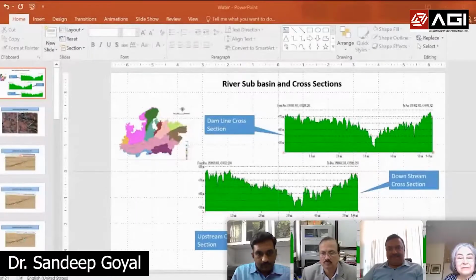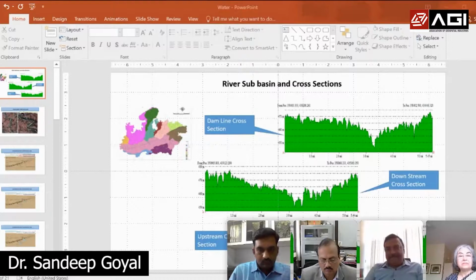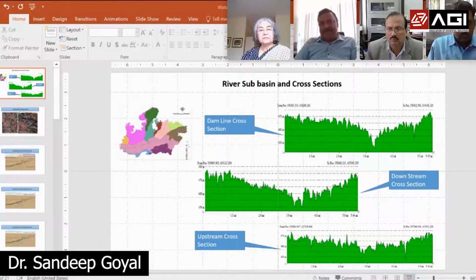Well, so these are some of the studies. Just about 2 years back, we started providing information to our WRD for planning of our water source structures, medium and major dams. Before construction of the dam, we create a virtual dam on a digital elevation model, draped with satellite image, and then we give them the submergence at every meter level, how much it will be. The plot details we overlay on top of that. In the last 2 years, we have planned about 170 such structures with WRD, the Water Resource Department.